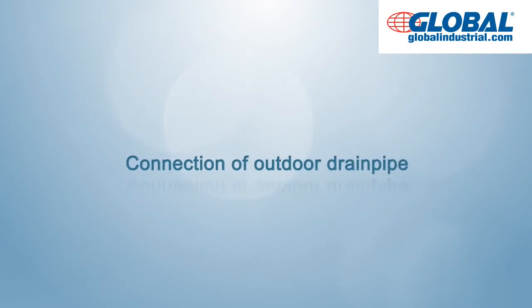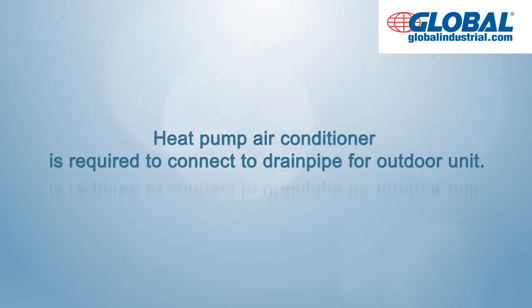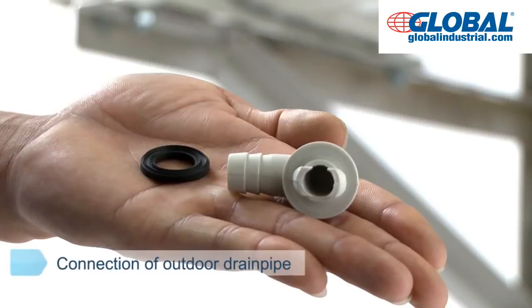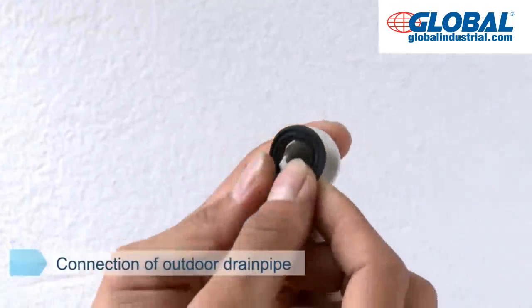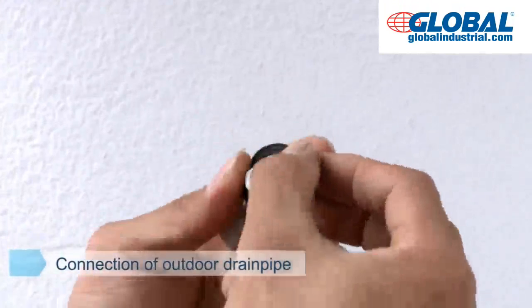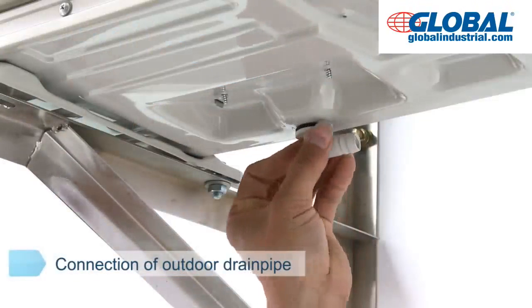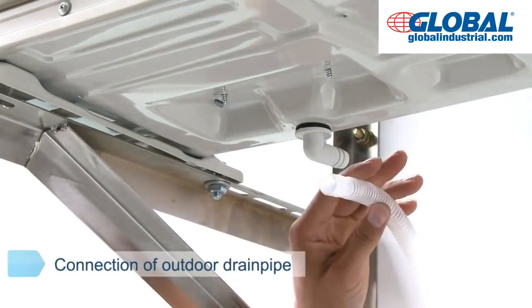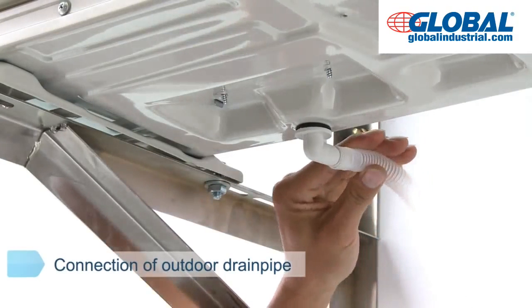Connection of outdoor drain pipe. Heat pump air conditioner is required to connect to drain pipe for outdoor unit. Gasket ring is sheathed on adapter of water outlet and turned 90 degrees after being installed in chassis through bottom of the outdoor unit. Drain pipe is sheathed and inserted into outdoor drain pipeline.